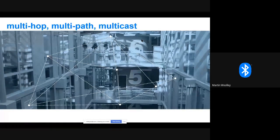And the big advantage of a multicast messaging system in wireless communications here is scalability, because I can occupy a radio frequency for 20 milliseconds to transmit one message, which will cause some form of reaction, a response, from potentially hundreds of devices all in one go, as opposed to sending 100 separate messages, if you see what I mean. So multicast gives us immense scalability, very efficient use of radio spectrum, and radio spectrum is a precious resource.